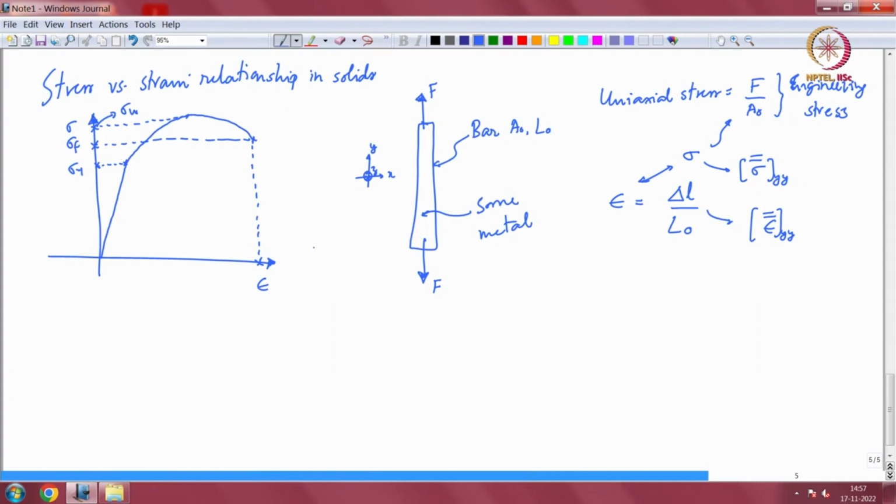Okay. Now all of the elastic stuff happens before the yield or the proportional limit, for instance before yielding actually occurs. So all of this remains elastic. So these are elastic strains. So for instance if you could do photoelasticity, you can do it here, right, these are all elastic. And the rest of it is all plastic, okay, so it is irreversible.